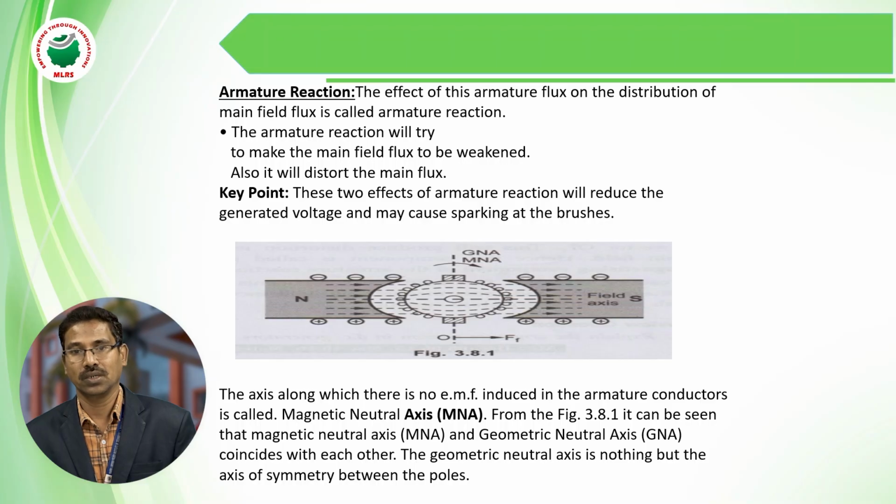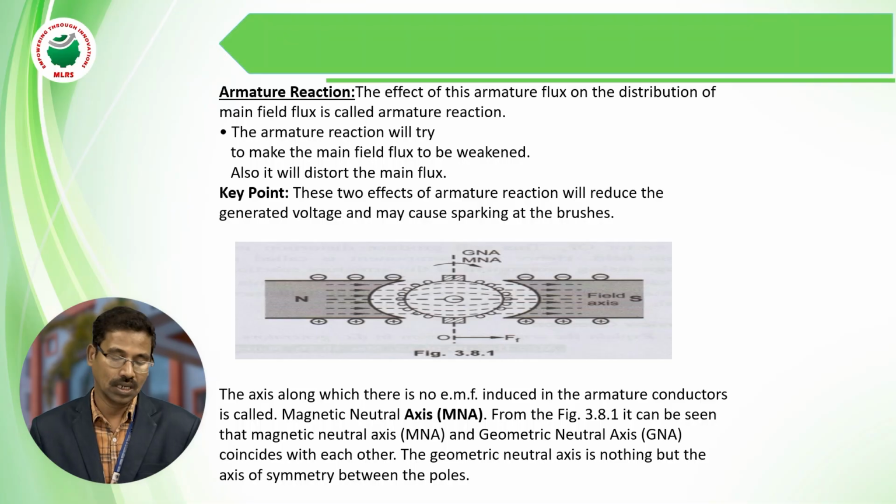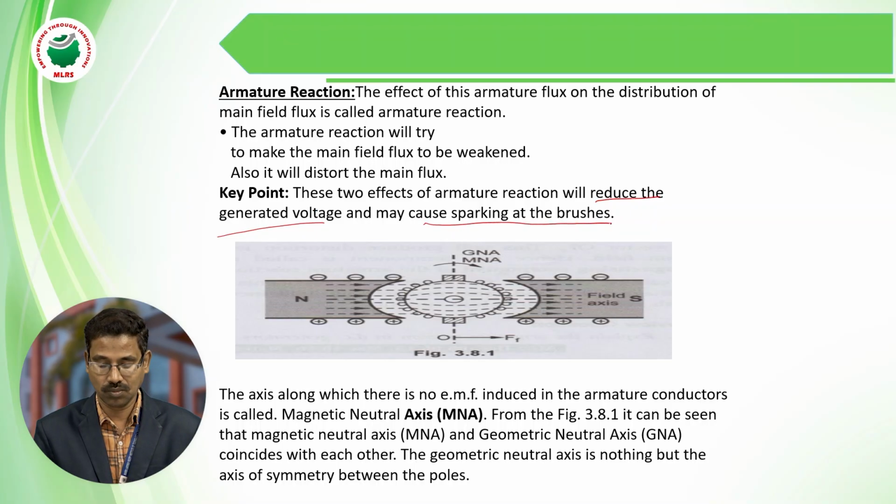So in order to reduce this, let us see how the armature reaction takes place. The first effect is the reduction in the generated voltage, which is the worst one. The second one is that, because of armature reaction, sparking takes place at the brushes. So let us study how the armature reaction takes place.